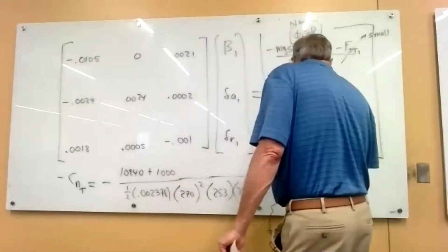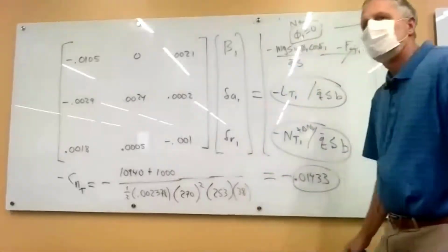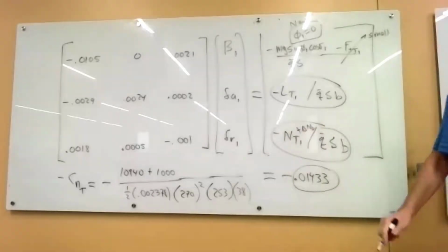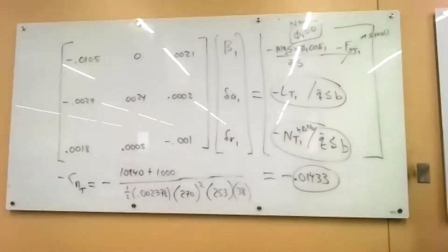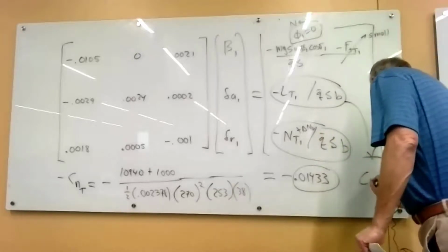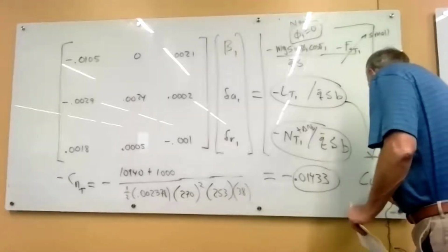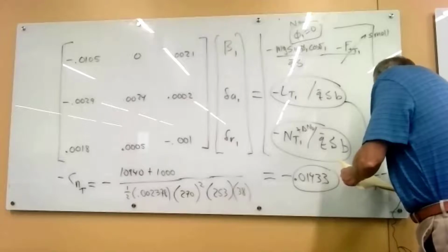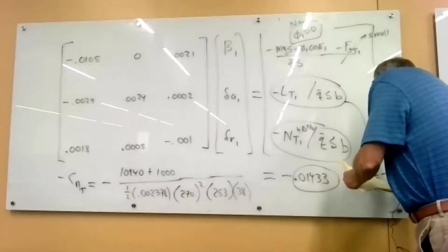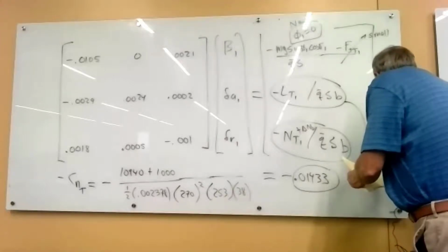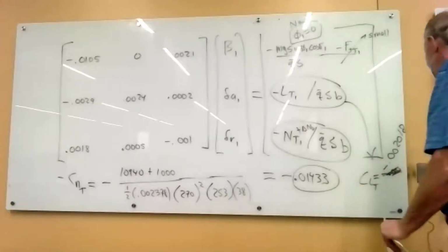So the yawing moment coefficient, due to the engine being out, is positive, but then this term has a negative number on it because we moved it over to the other side of the equation. And if we calculate this other number up here for the roll, plug in the number for that, we get minus 0.002. Let me write it big, minus 0.002018.